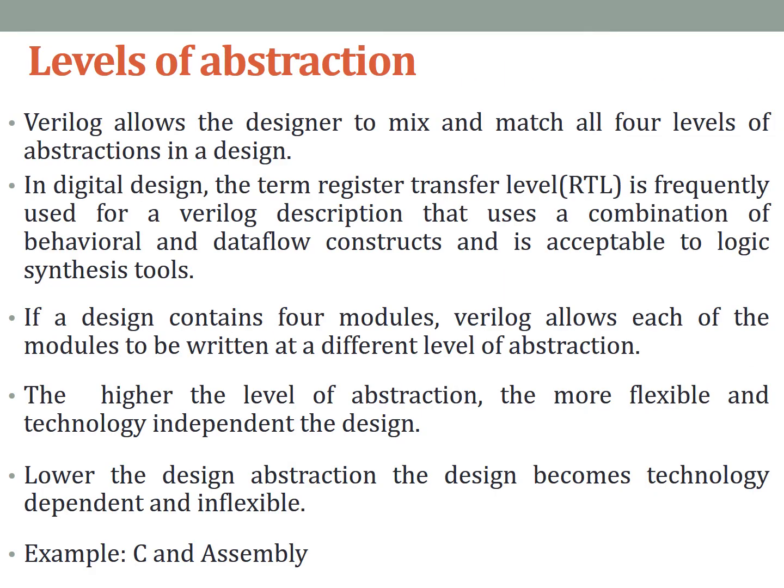So a summary about the levels of abstraction. We can mix and match any of the 4 levels of abstraction. So RTL, that is the register transfer level, is a description which combines data flow and behavioral description to make it suitable for synthesis tools. If we are writing a design with 4 modules, Verilog allows all the 4 modules to be written at different levels of abstraction. The higher the level of abstraction, the more independent it is from a technology.